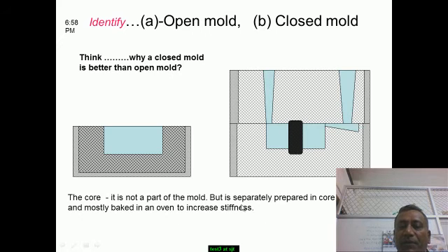It is to be mentioned that this is called the core. This core is also made of sand material only, but of slightly higher quality, having more strength than the basic mold material. Because of the presence of this sand core, the molten material just goes around it and fills up, and after solidification we will end up with a through hole.